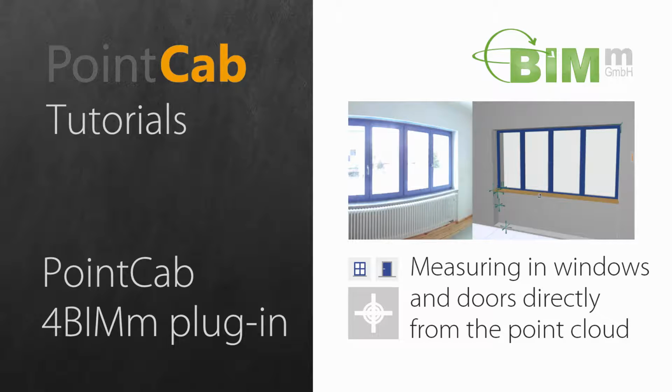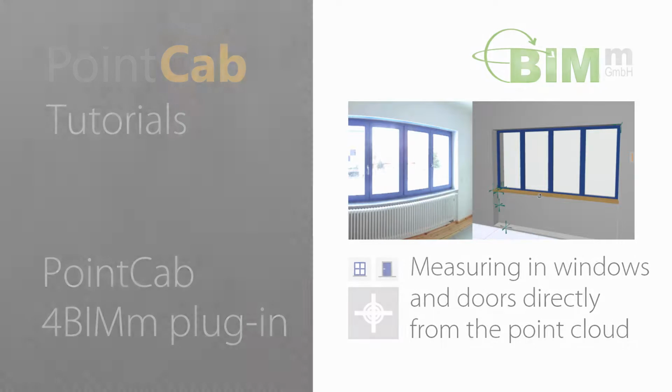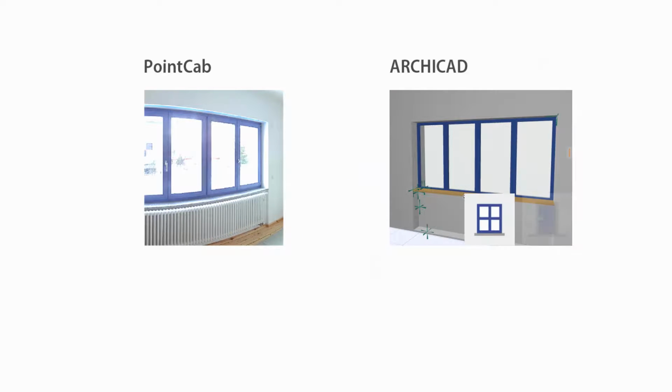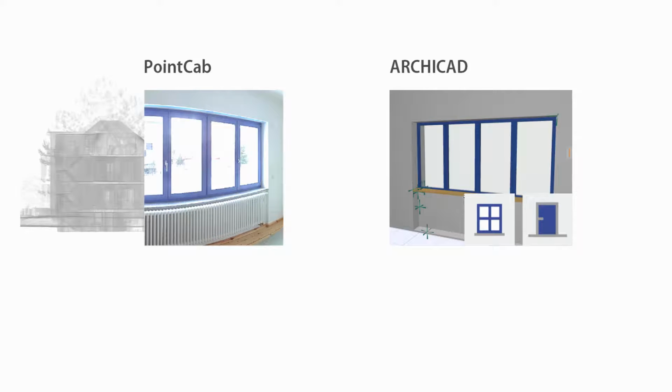Now that we have already created story levels and walls, we now want to insert windows and doors. We will create these directly from the point cloud without having to import the point cloud into ARCHICAD. This is one easy way to bring individual components into the CAD system.